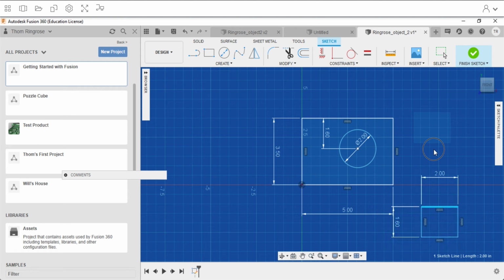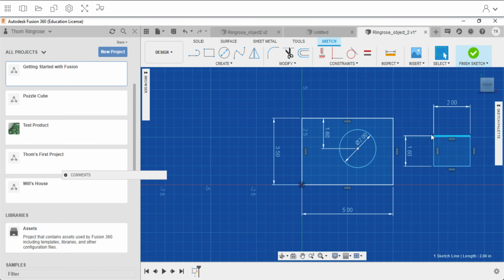And look, I've got this lovely rectangle that I can move, because again, we have no X or Y value associated with it. All that we have is our dimensions. But I want this rectangle to be connected to this circle. So what I need to use are what are called our constraints. And this is going to let us lock these pieces together.